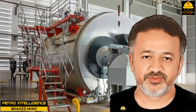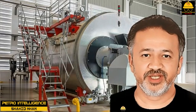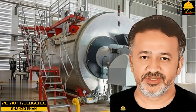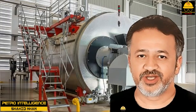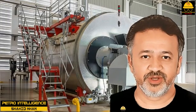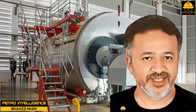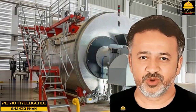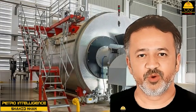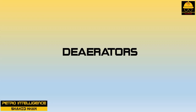Our favorite reuse of such contaminated condensate is as a replacement for velocity steam in the heater tube passes of a fired furnace. There is little danger in injecting a controlled amount of water into a furnace inlet when using a properly designed metering pump. Such pumps typically have a capacity of 1 to 10 GPM and provide a set flow regardless of the discharge pressure. The injected water flashes immediately to steam inside the furnace tubes.